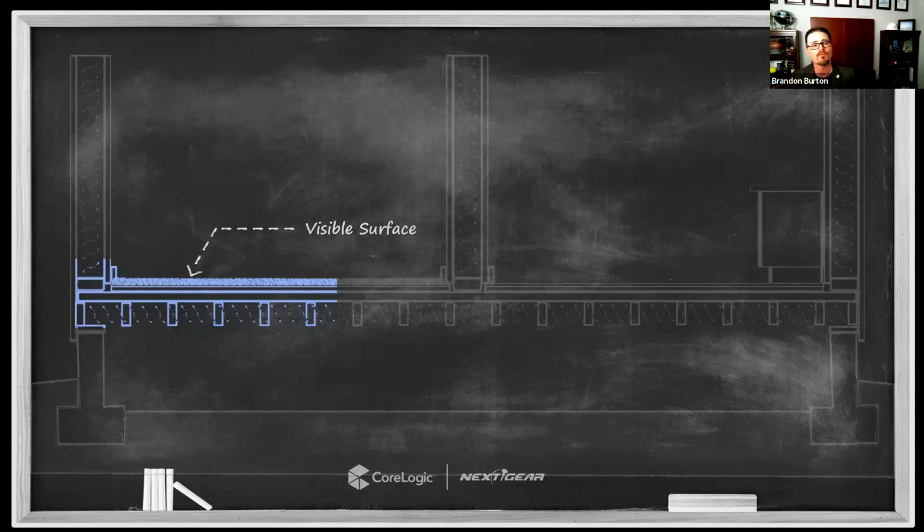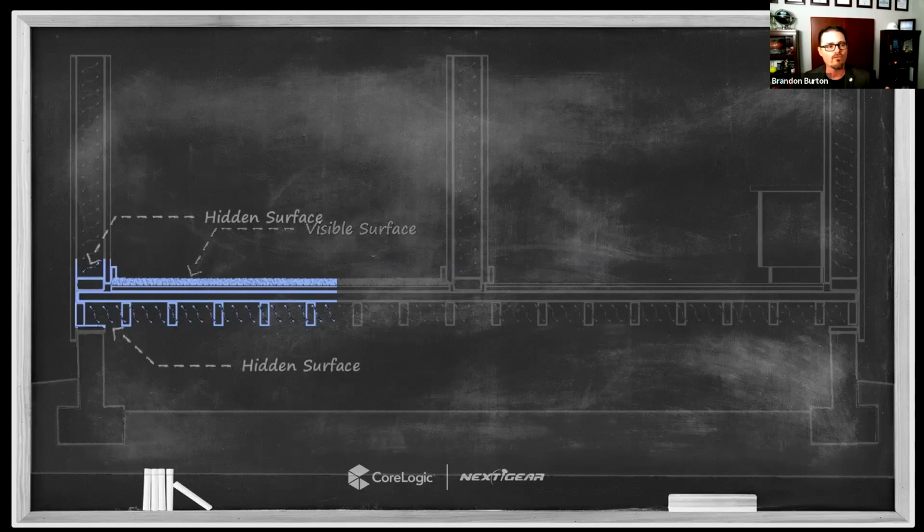In terms of air movement, what that means is I need to understand what are the wet surfaces inside of these cavities. Is there water evaporating from those surfaces? And if that is true or possible, then we need air movement to evacuate the water that's evaporating inside those spaces as well. Every wet evaporating surface should have air movement removing that evaporated water and replacing that with the warm, dry air created by either dehumidification, ventilation, heating systems, whatever your humidity control resource is.